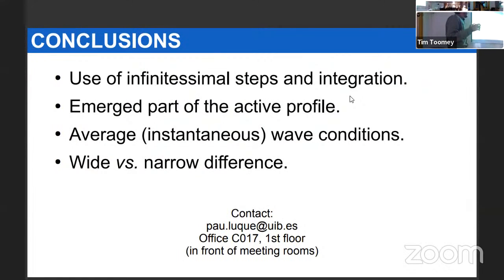So to end, again, we should use sediment transport in general, but for those cases that we are interested in using a simple model, so equilibrium beach profile theory, we should have in mind these points. The first thing is that we should use infinitesimal steps and then integrate them in order to provide results the most accurate possible within the field. And then it's important to take into account the emergent part of the active profile and also instantaneous conditions, which result in average wave conditions instead of extreme ones.